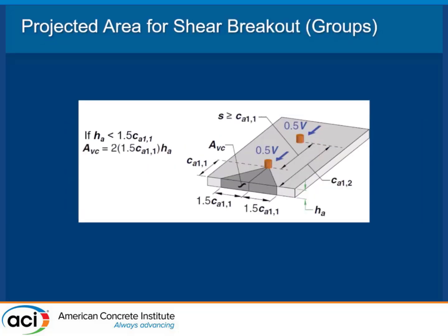And we have three different modes here, so you have to look at how your base plate or your anchor system sits on top of whatever element you have. A lot of times when you have a base plate with oversized holes, if the oversized holes are minimal and there will be minor deformations, you can assume that half of that load will go into the front anchors, the anchors closest to the edge, and the other half will go in the back.